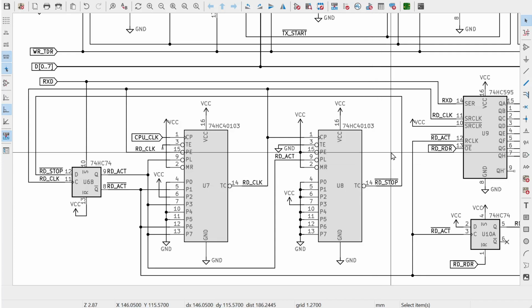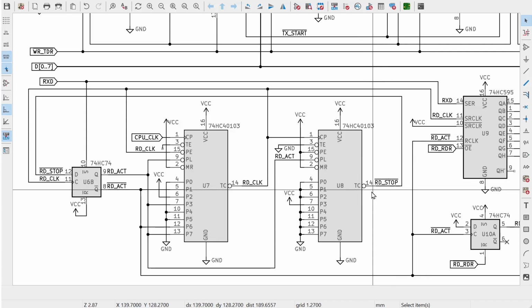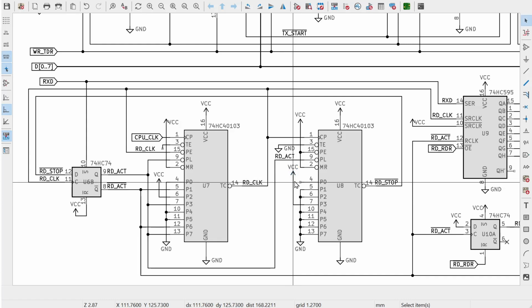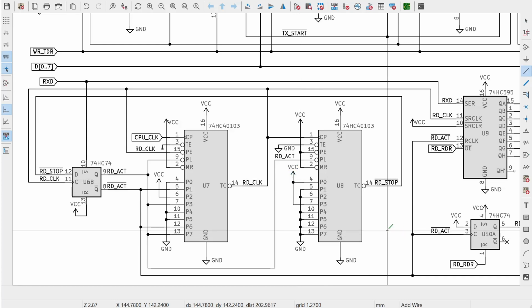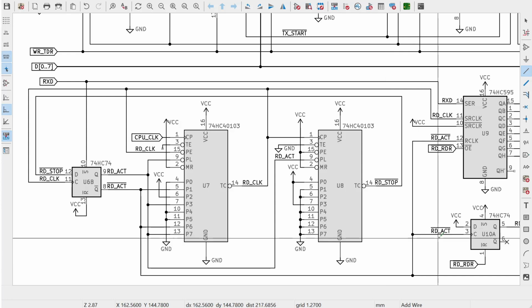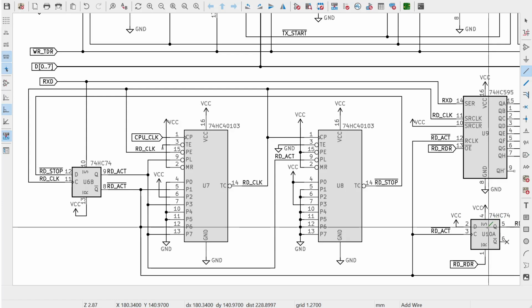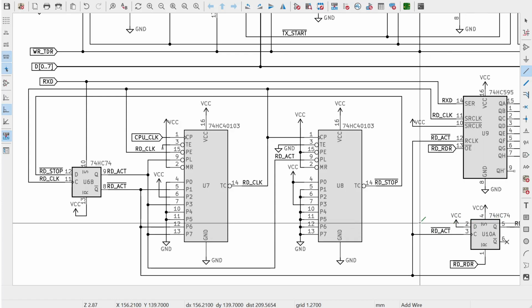The change I made to the circuit to correct that, though, one thing I did was actually changing the count value here to be 9 instead of 8. So I think what I probably had previously was it was probably triggering all sorts of things like the receive data register ready signal too early.